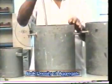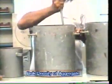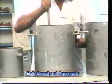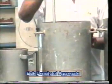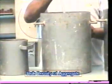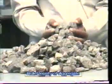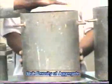Now the measure shall be filled with the material in about 3 different layers, each being tamped with tamping rod for 25 times. Here this tamping is for best possible natural orientation of aggregate particles, not for compaction.